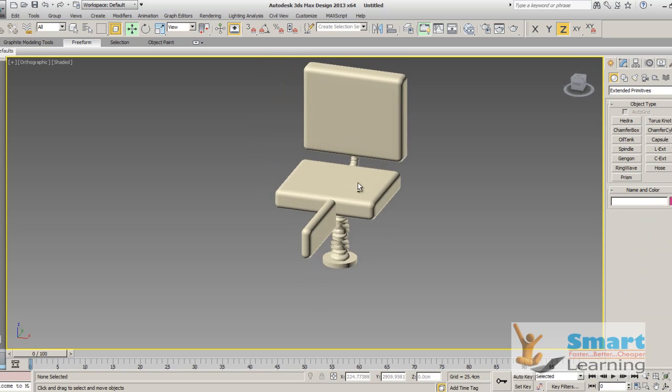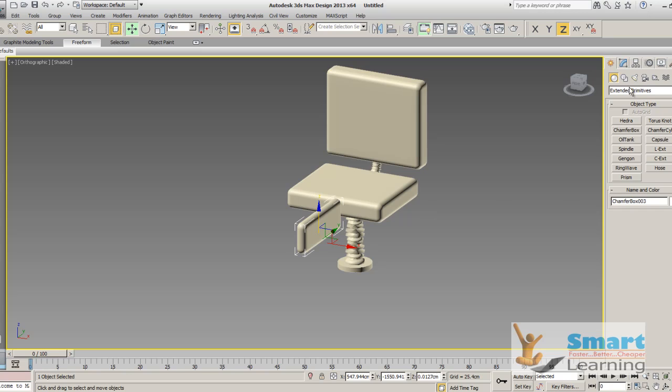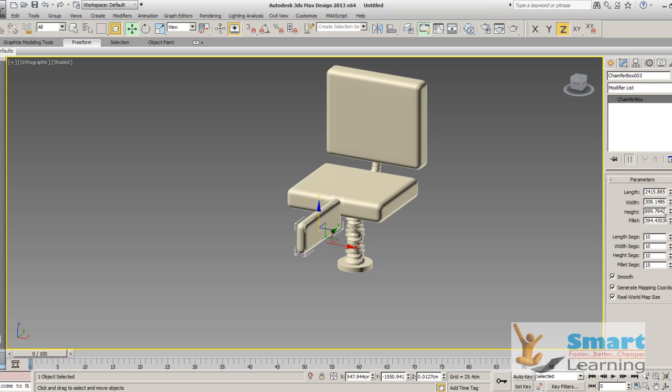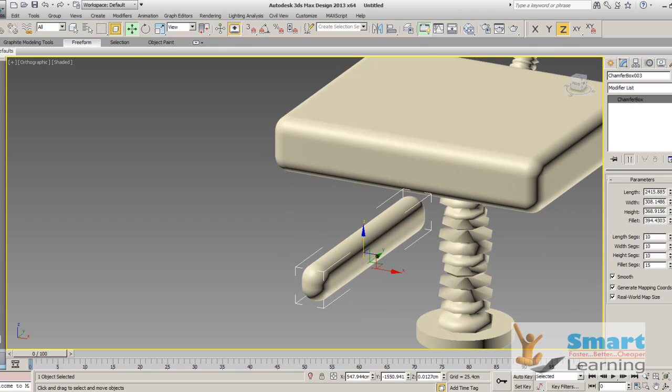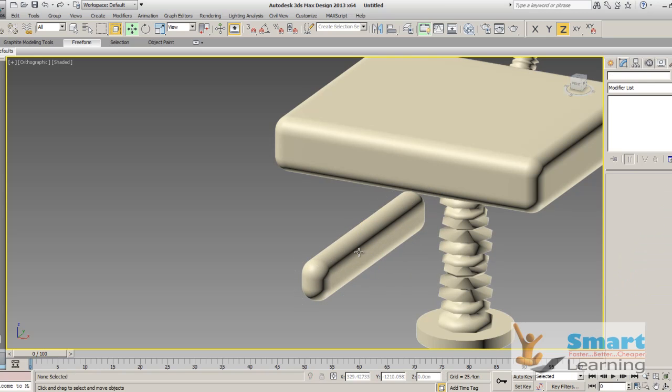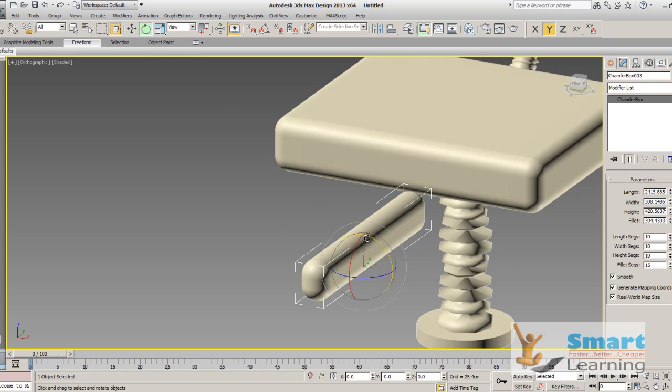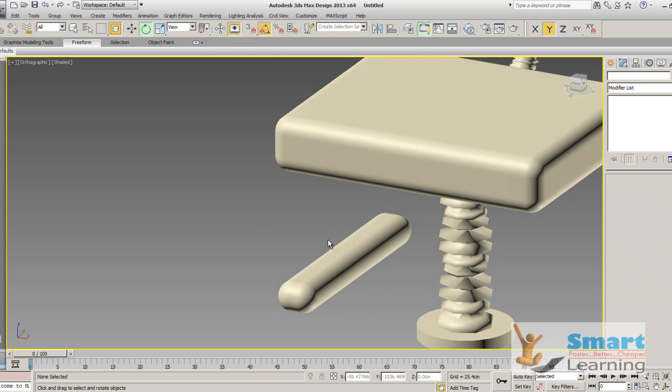I'll set different parameters here. So like heights will be of this magnitude, and all these frames are okay. So I'll apply a taper, and these all dimensions little bit I'll move here. I'll be going to rotate, angular snap, so this will be okay.